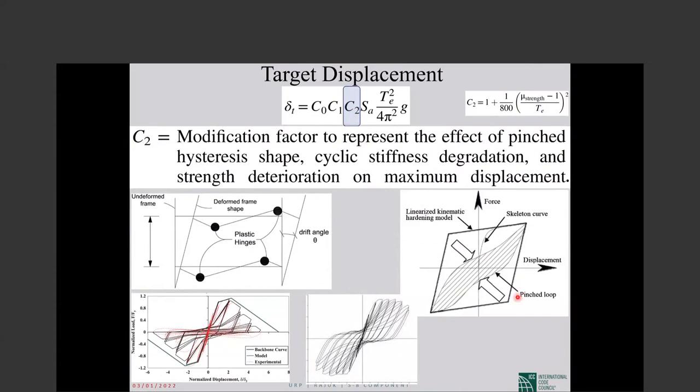It shows the effect of all the deficiencies in the detailing that can increase the displacement of the building. Because it is acceptable for us that when an earthquake with a specific amount of energy is applied to the building, specific fuses, specific plastic hinges, should absorb that energy.